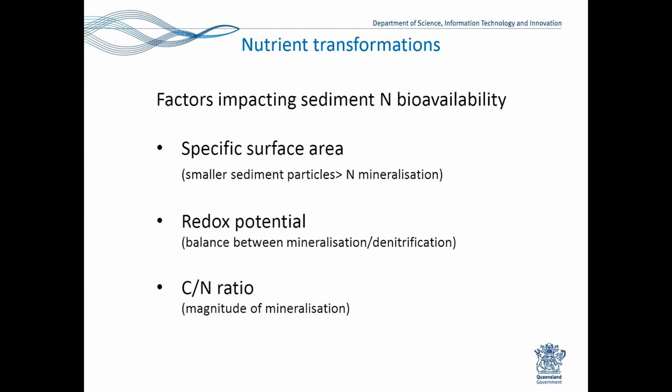Carbon to nitrogen ratio, also hugely important. If you have a large carbon to nitrogen ratio, probably something greater than 20 to 1 for instance, you end up with what we call net nitrogen fixation. There's not enough nitrogen being produced to be taken up by our crops or macrophytes or whatever, because the bacteria, as they're chewing into the carbon, oxidising the carbon, need that nitrogen for their metabolic processes, so they tie it up.